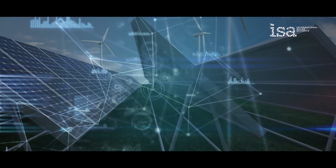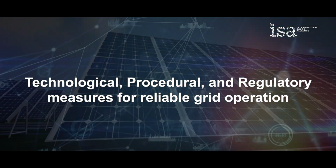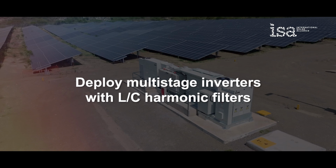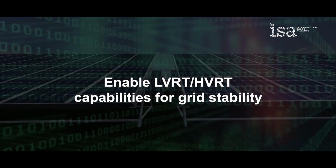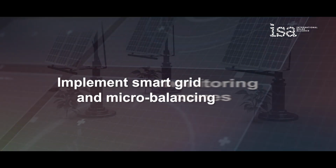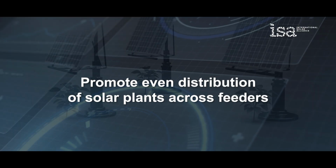To mitigate challenges, utilities and developers must adopt technological, procedural, and regulatory measures for reliable grid operation. Deploy multi-stage inverters with L/C harmonic filters. Enable LVRT, HVRT capabilities for grid stability. Implement smart grid monitoring and micro-balancing zones. Promote even distribution of solar plants across feeders.